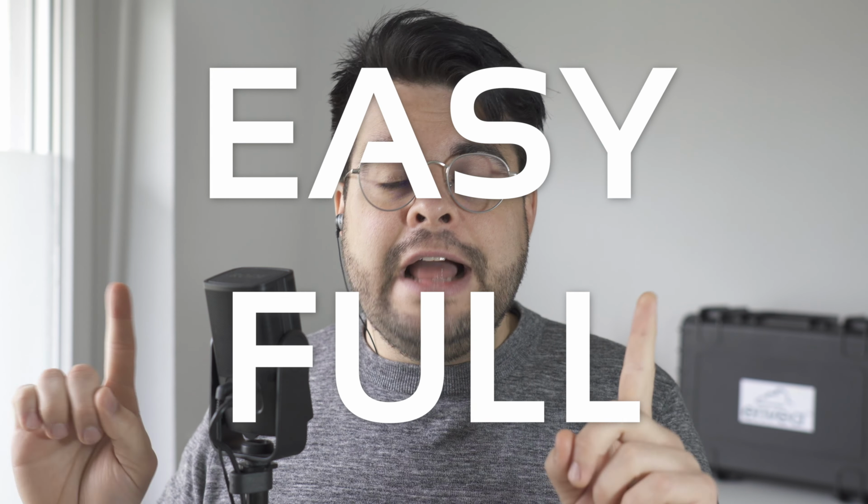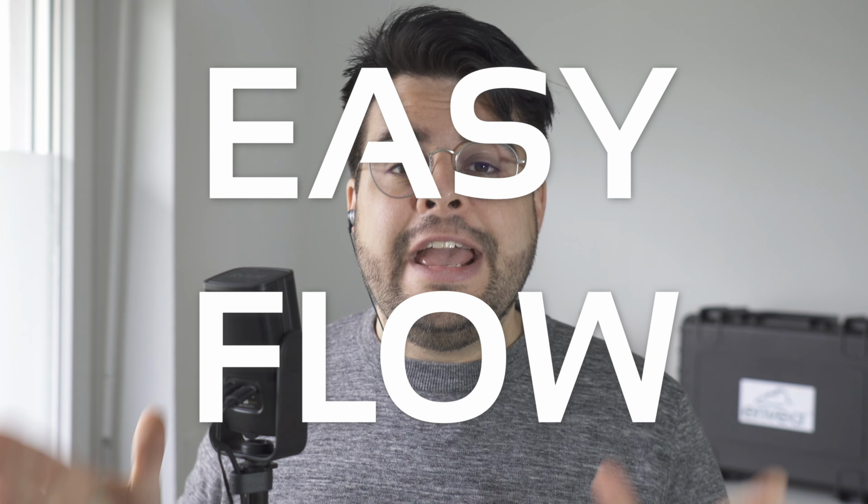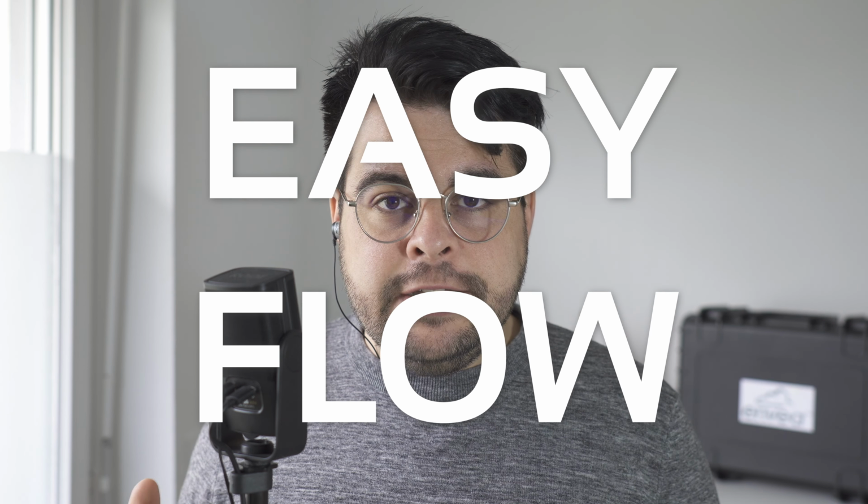Static, you basically fill the sensor with the material, and by pressing one button, you tell it this is a full sensor and it's basically ready to go. This calibration process is called easy full calibration. It considers that the sensor is loaded with material and the velocity measurement happens only after the calibration. The most recommended method is called easy flow calibration, which happens dynamically. We have to convey material through the sensor and then store data and find calibration points. This is what we're gonna do here now.